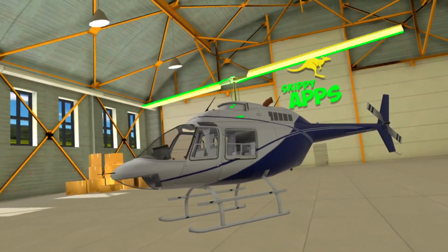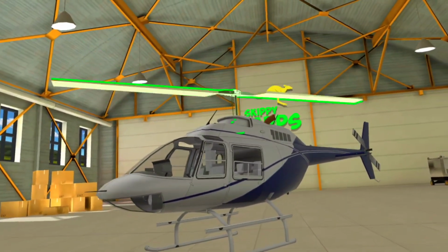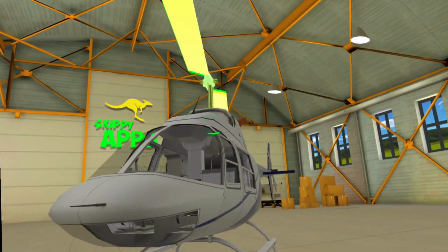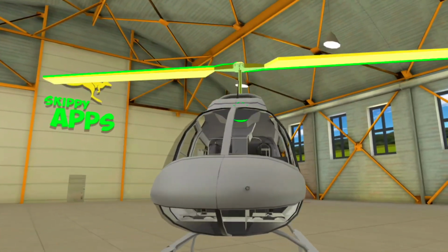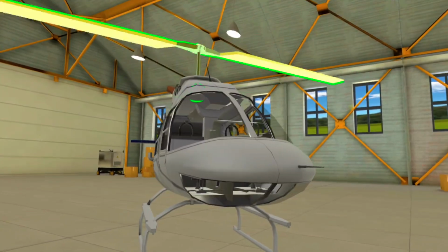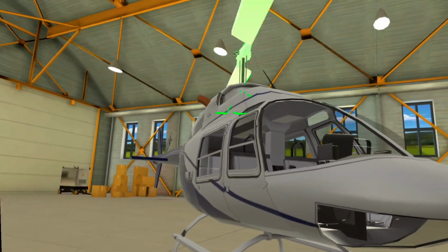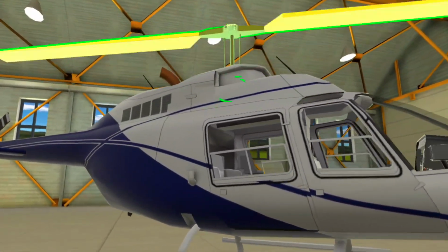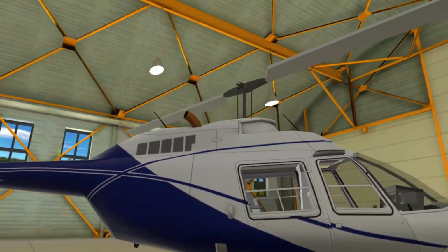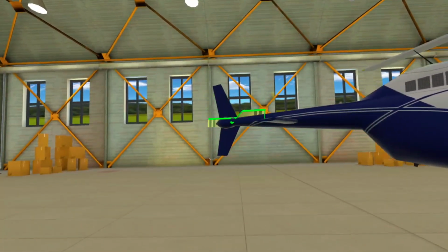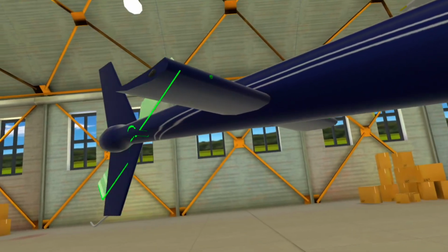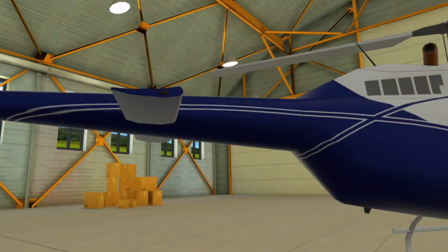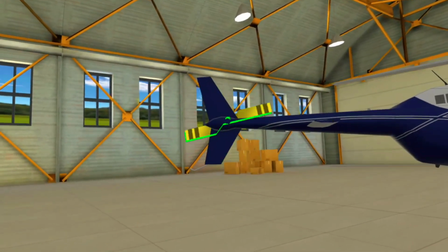The helicopter typically features a 2-blade rotor system, which provides a balance between performance and simplicity. Main rotor blades are constructed from lightweight composite materials to enhance strength and reduce drag. The main rotor blades create lift by rotating through the air, with their angle of attack adjusted to control flight. The tail rotor counteracts the torque generated by the main rotor, preventing the helicopter from spinning uncontrollably. It enables the pilot to control the helicopter's rotation around the vertical axis, allowing for precise directional movement.